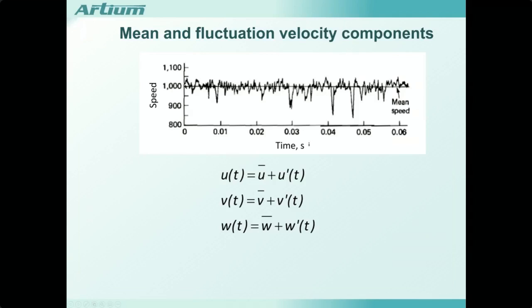And what you'll see is the mean is fairly stationary, and on that there are fluctuations. With hot wire anemometers, which was the earlier and still used method, you get a continuous reading of the turbulence fluctuations, so you get a direct time average and time response.